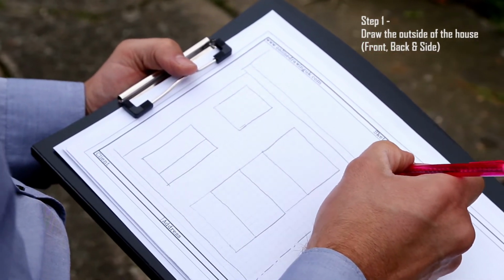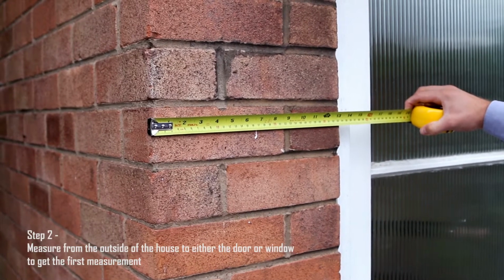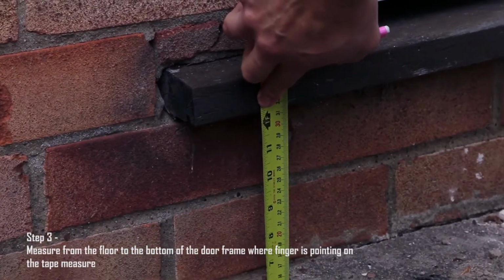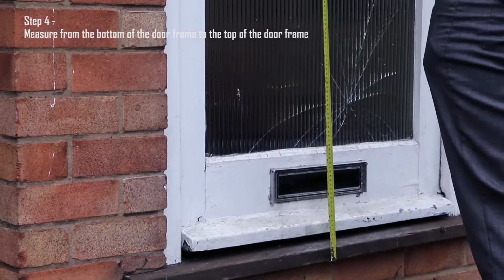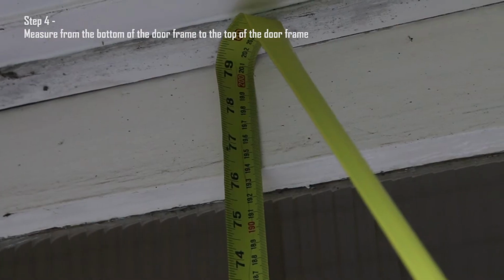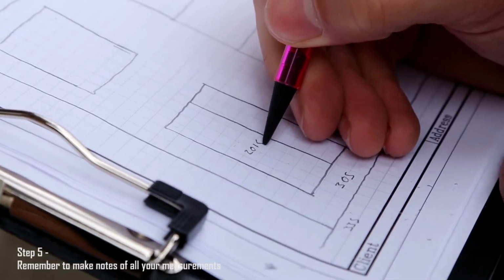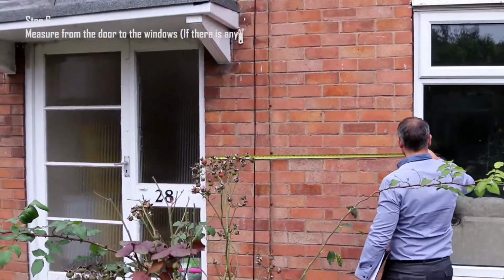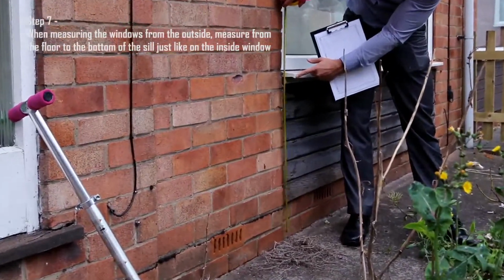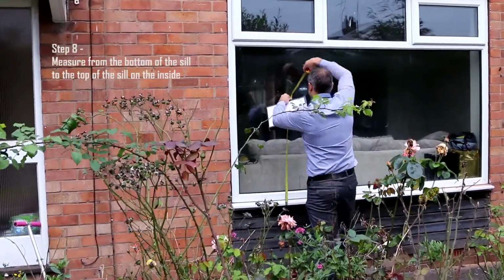Outline your elevation. Some reference width dimensions to go on the plan. Measure to the underside of the door. This will determine the floor level. Measure from the bottom of the threshold to the top of the door externally. All heights can be written on the outline of the drawing. Some reference width dimensions can be used. Just like inside, we take reference heights from the outside.